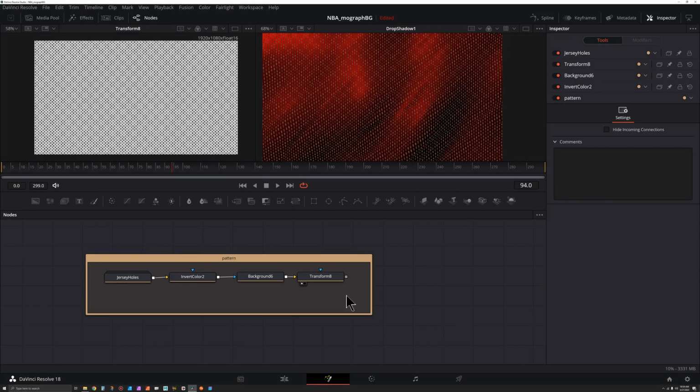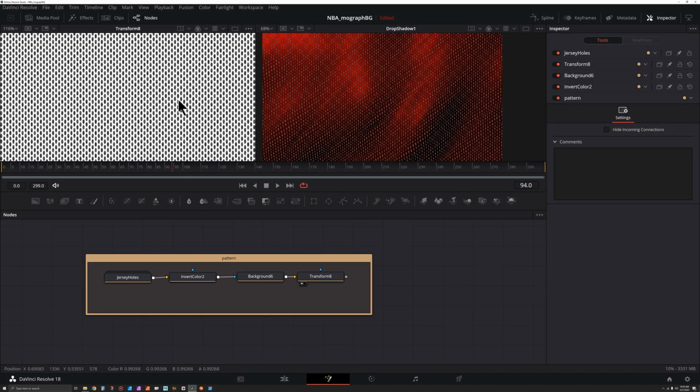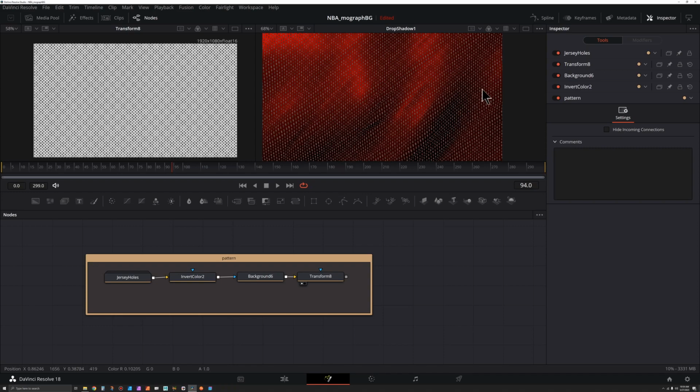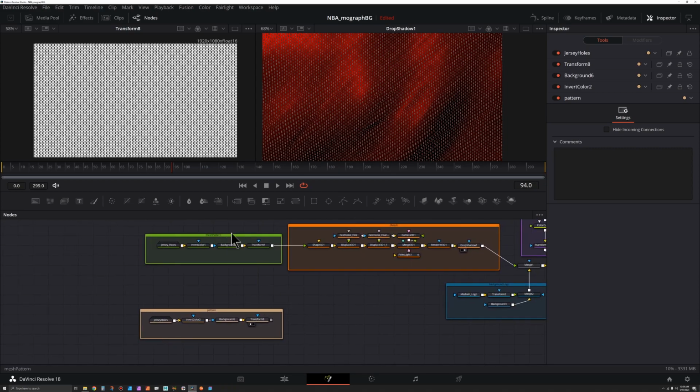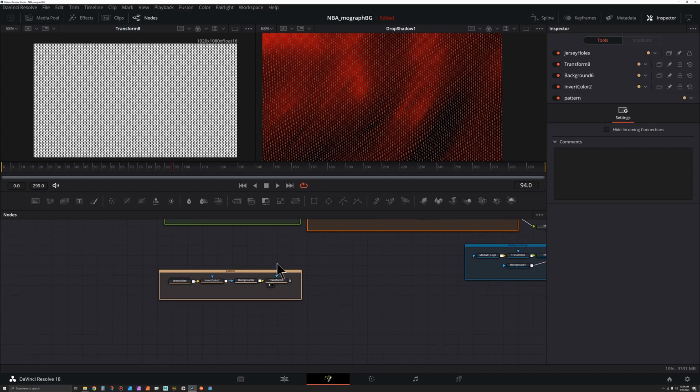In the previous video of this series, we created this pattern that you see on the left, and now let's make it three-dimensional like what we see here on the right. So I'm going to zoom out here and we can see this is what we created before. I'm actually going to color code these so everything stays lined up. You could right click on your underlay, go to set color, and I think it's maybe this green.